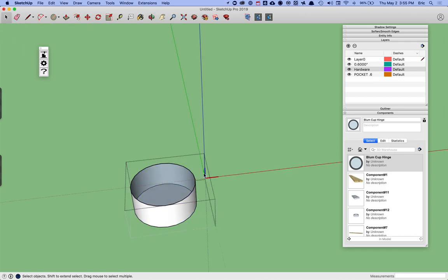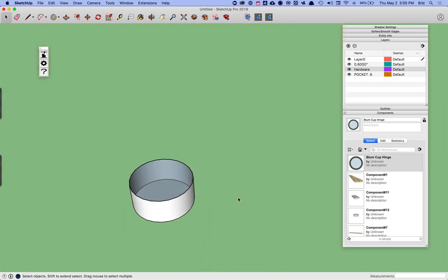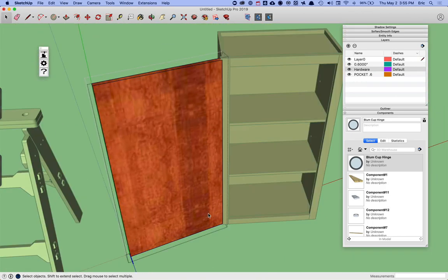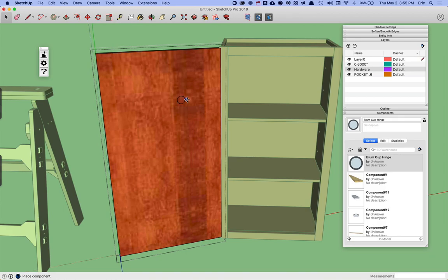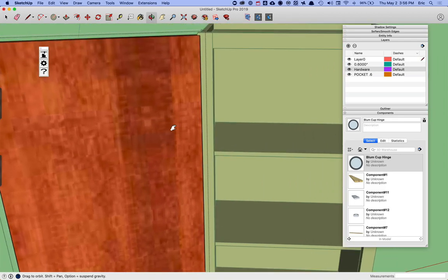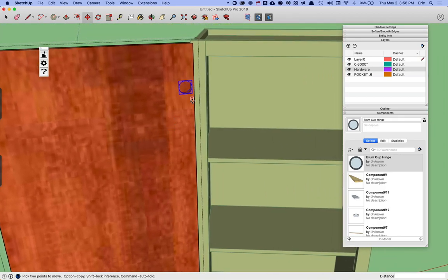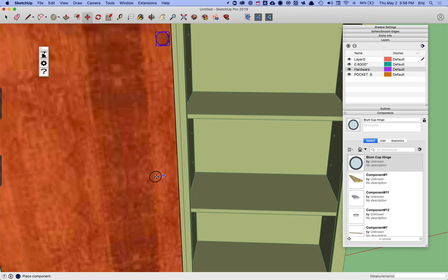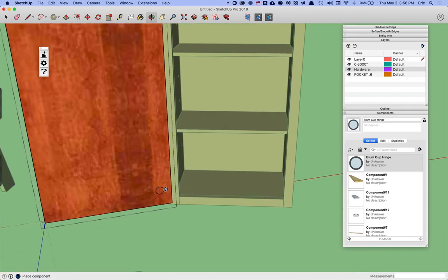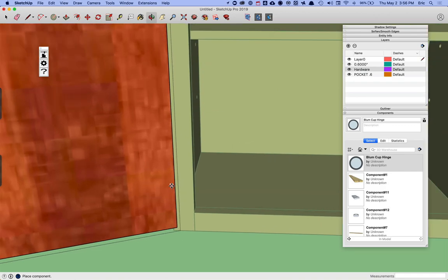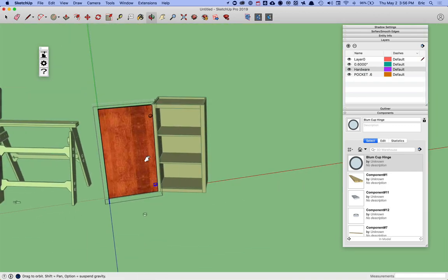So if I double click, you see I've made the origin sort of off to the side. It's on the same plane, but what that'll do is now when we go into these components, it'll be offset from my mouse pointer that exact amount, and you'll now be able to go in and have these things evenly spaced exactly off of the side of the cabinet door.